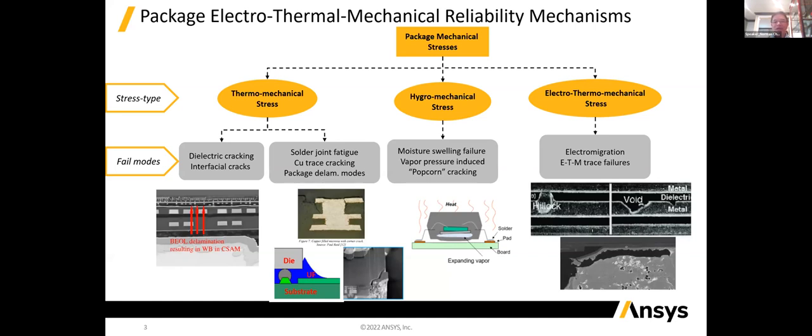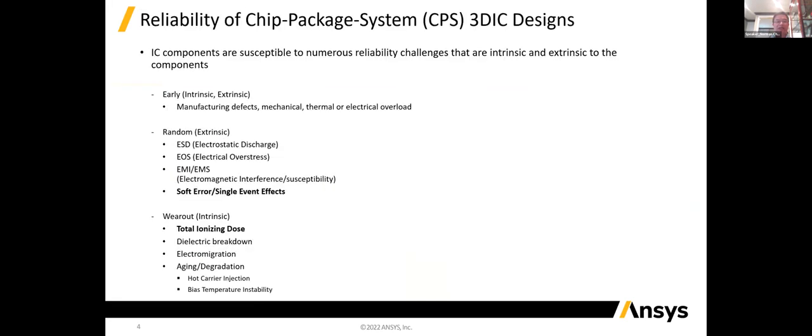And this problem, electromigration, has a new challenge in terms of the TSV, RDL layer, and the fan-out WLP design, because the shape of the metal conductors is not rectangular. It can be 45 degrees. It can be a big piece of metal. So in terms of the calculation of electromigration, the direction of the current is not certain, and that becomes a new problem when we're going down to 3 nanometer and 2 nanometer designs.